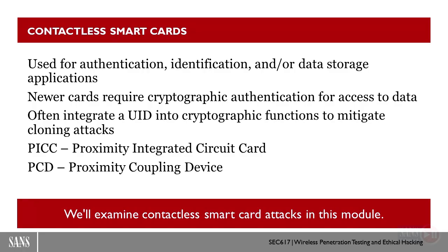We're also leveraging some additional mechanisms to include more security, such as a unique card identifier integrated into some cryptographic functions. So we have some input seeds, if you will, to those cryptographic functions available from the cards themselves. With the intent of being able to mitigate card cloning by preventing card writes and using different entropy into those solutions that we may not be able to recreate.